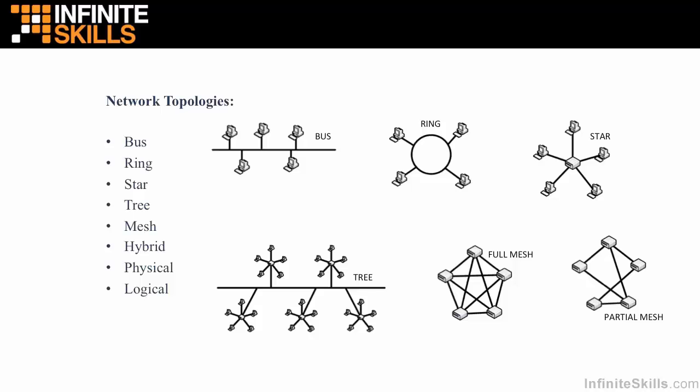Now this is a core backbone, that's the bus part of this, that we would snake through the office, if you will, and then you would tap into that bus, that backbone, with the different nodes that you want to connect to the network. Now the linear bus has the problem that it requires terminators at the endpoint, because here's what happens.